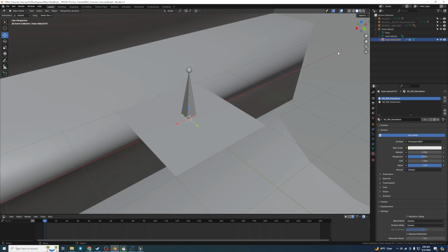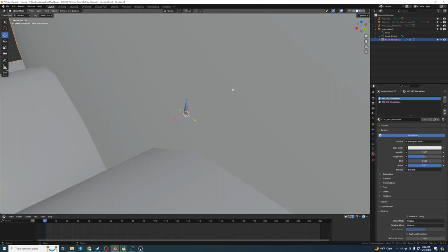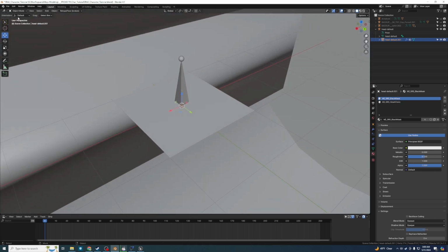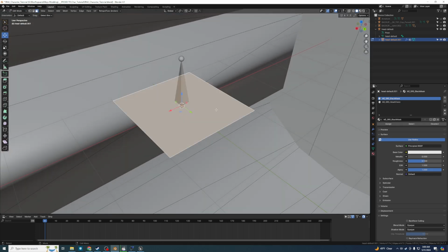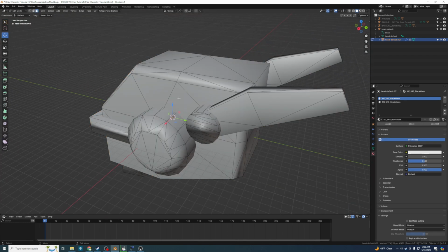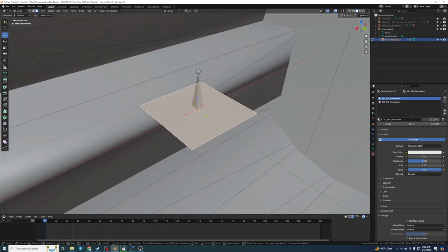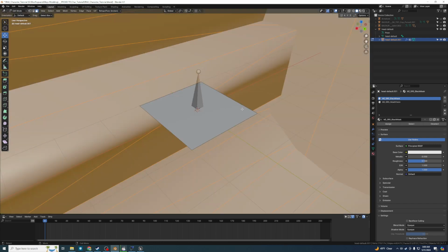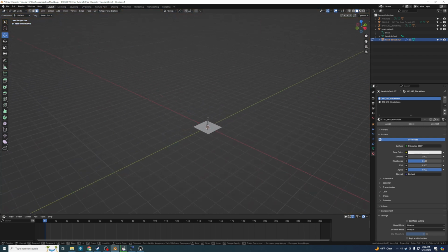What we'll do is click on the model, so we have it selected, go into edit mode, click this face, and then in the material tab down here, just assign this first material, just like that. And then we'll select everything else. We can just hit Control I to invert everything, and then just delete all these faces like that.